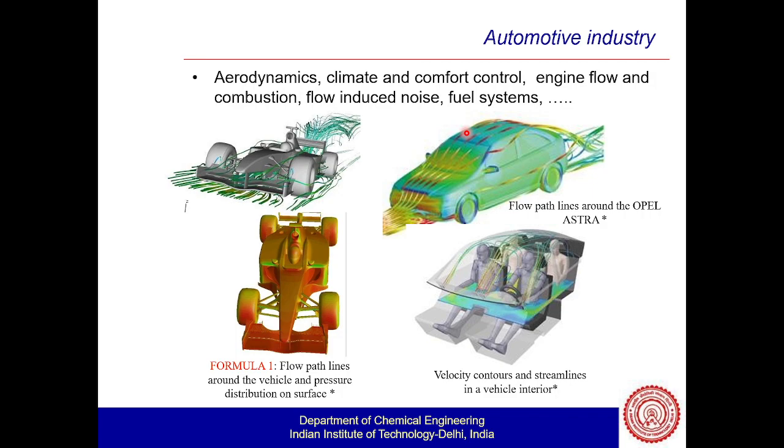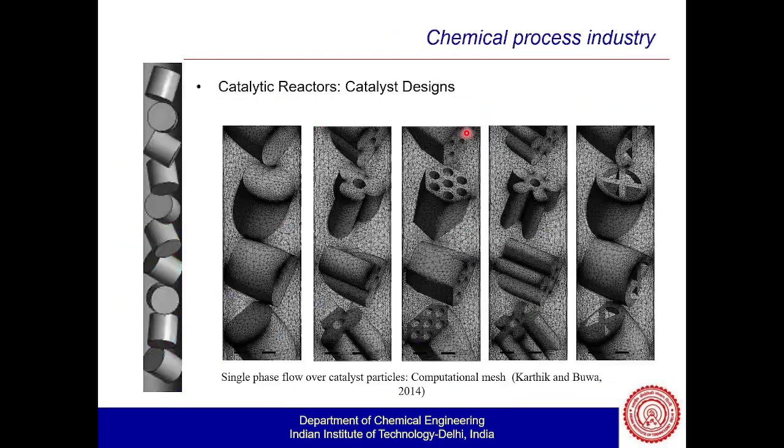It depends upon the flow problem. For example, if a reaction is happening for a single bubble which is rising in a liquid, it will not take much time. But if it's a reaction which is happening in catalytic flow reactors, these simulations are typically expensive in nature because, as you can see from here, the meshes are basically tet meshes. So they are not hex meshes. The problem is that, depending upon the meshing of the system rather than these equations, the meshing plays an important role because it interferes with your convergence. So more time is required in order to converge a solution.